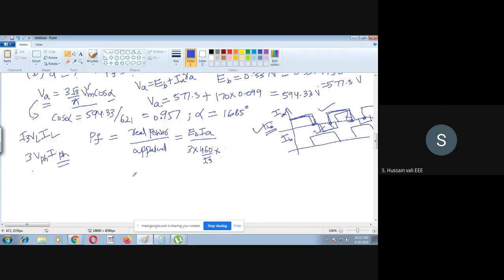So what is the RMS value? You will get the RMS value of the phase current. I will write the formula directly: IA into (pi minus alpha by pi) whole power 1 by 2. This is the formula you will get when you find the RMS value. I'm giving the hint here on how to find the RMS value because the current is continuous and you take it as ripple free.